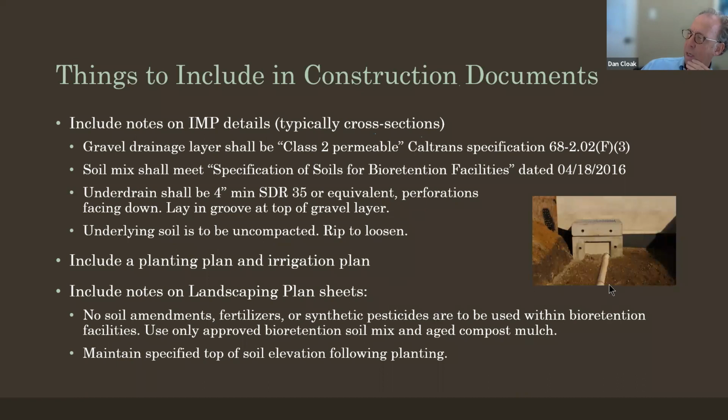Is this technique that here's the gravel layer installed, and then a groove is dug in it with a shovel, and this is laid down so that those perforations are at a level where the amount of interstitial space in this gravel, basically this subsurface reservoir, is maximized, and you're getting the benefit of storing and promoting infiltration to the native soil of the absolute maximum amount of volume here, while at the same time preventing the fines from your soil layer, which is going to go here, from getting into the underdrain and being washed out.